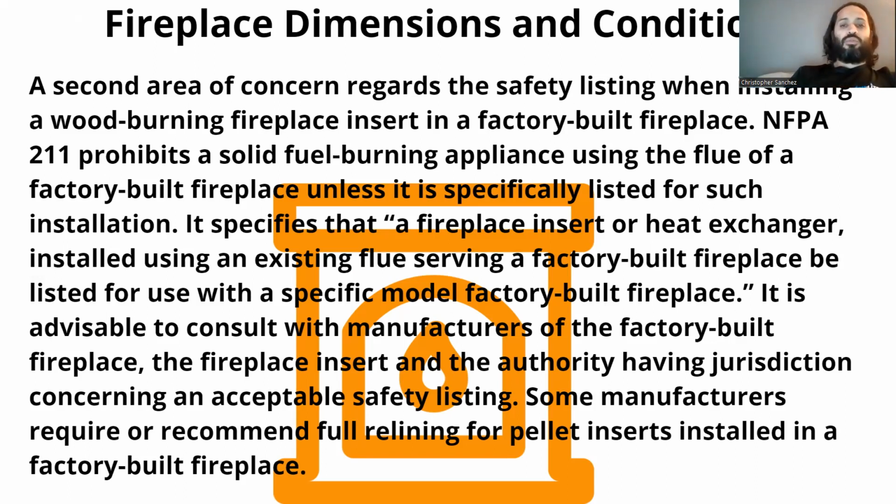It is advisable to consult with manufacturers of the factory-built fireplace, the fireplace insert, and the authority having jurisdiction concerning an acceptable safety listing. Some manufacturers require or recommend full relining for pellet inserts installed in a factory-built fireplace.